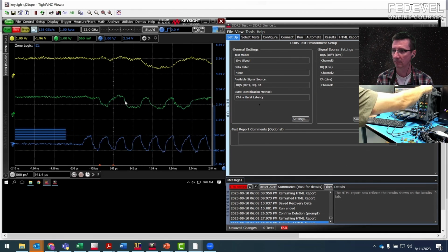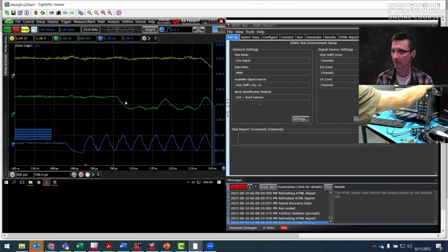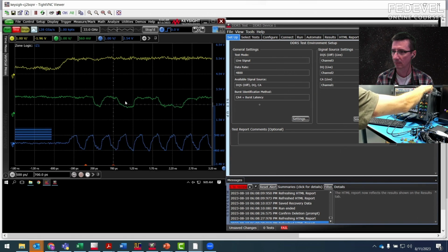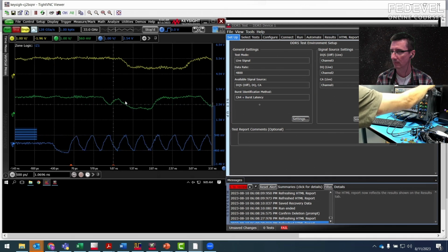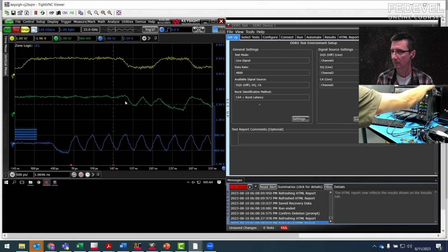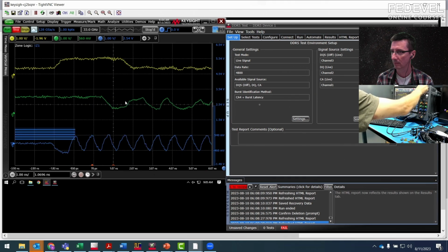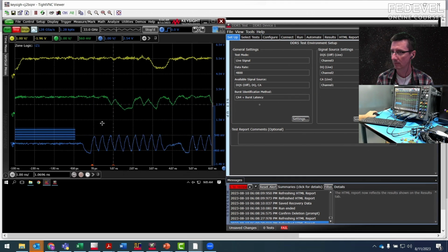Now, if we move this to the right, so if we find one that, go back a little bit more, maybe zoom out a bit. Okay, here we go. This is good. This is perfect. So DQS, our strobe, is toggling before the data starts. The data's latched in, boom, boom, every rising, falling edge, boom. We get that bit, we get that bit, right? So rising, falling,